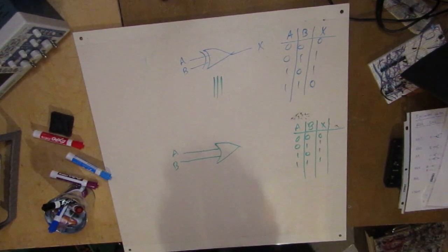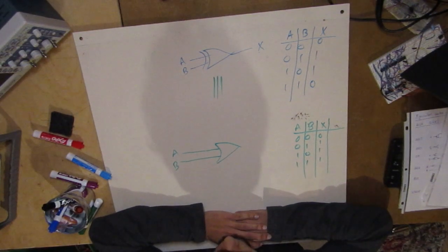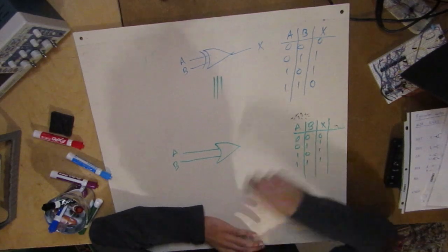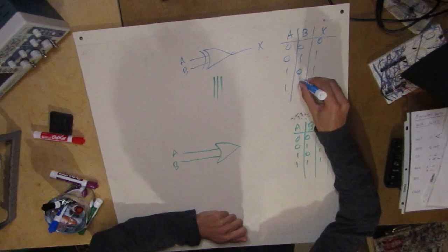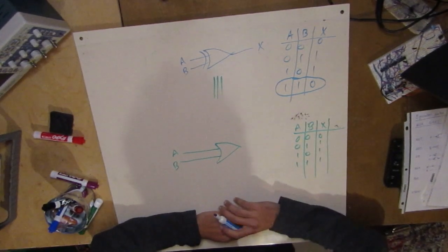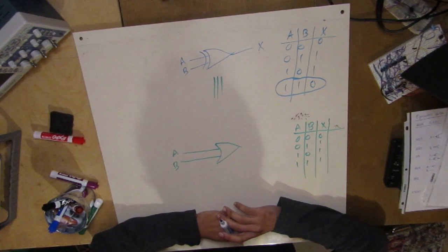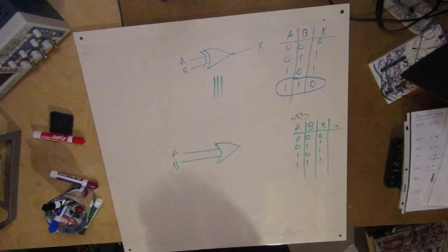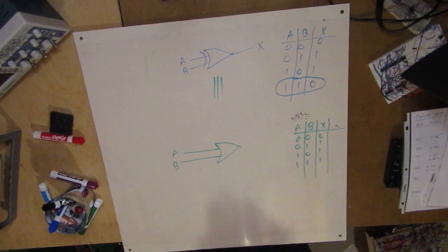All it says is that the NAND gate could be thought of as an OR gate that's looking for zeros, right? We want to cancel off this one condition. Like, we want to just inject a 0 when it detects that a 1, 1 comes. Okay? How do we do this? This is where we add a NAND gate. Because the NAND gate is just looking for the inverted zeros.